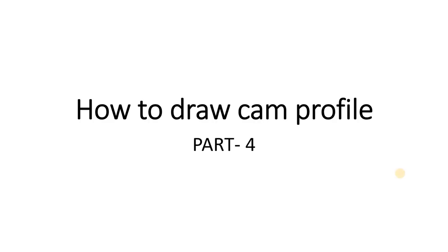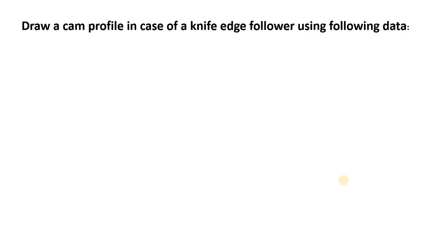In this video, we'll try to understand how to draw a cam profile. Now we have to draw a cam profile in case of a knife edge follower using the following data. Minimum radius of the cam is 5 centimeter.